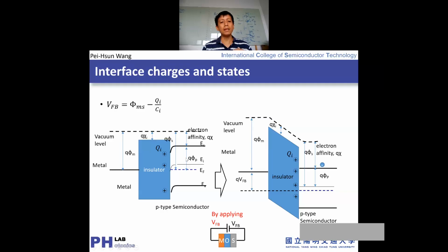And if you have this surface charge, as we mentioned, we get the same like a phi S and a phi N, but you get a certain banding, like we get the surface charge, positive charge here. We can have certain negative charge along the surface. So you need to consider additional charge, entrapped charge along the surface. So previously, if you do not have any interface charge, you will get a flat band voltage equal to the difference between metal and the semiconductor work function. And here we assume the work function between phi N and phi S are the same. But since we get a surface charge, we accumulate additional negative charge here. So you can see there will be some Fermi level, which is slightly higher than Ei.